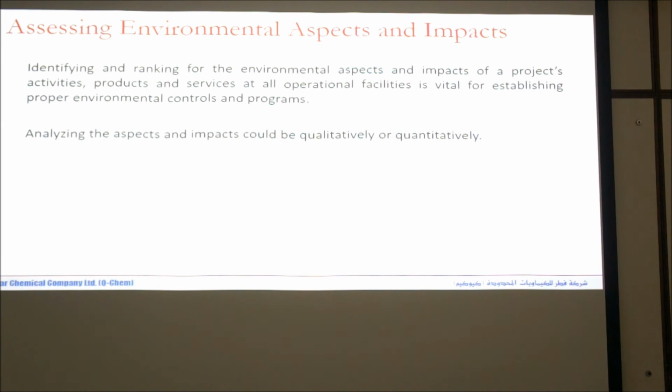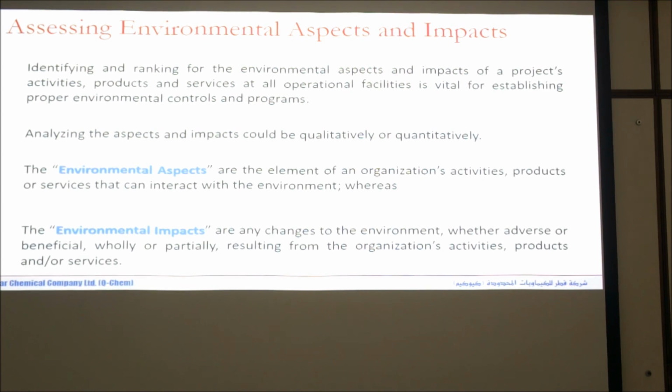So fuel gas is cheaper, but the boiler itself, working with the fuel gas, is more expensive. So the decision you have to make is whether you go with your capital and buy the more expensive one, which will pay itself back in years to come, or not. Now, say for example you select the fuel gas, whether you go with the dirty fuel or with the clean fuel. And clean fuel is more expensive. Maybe I can go with the dirty fuel and add some controls in my design to still emit what is acceptable. Maybe not. Maybe I have to pay more. So all of that you take into consideration, and then answer back at the end whether your design is going to be profitable or not profitable.